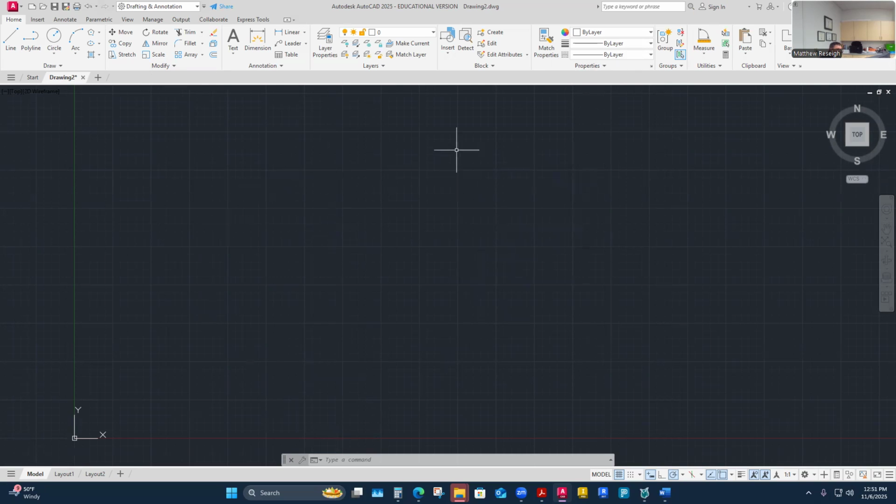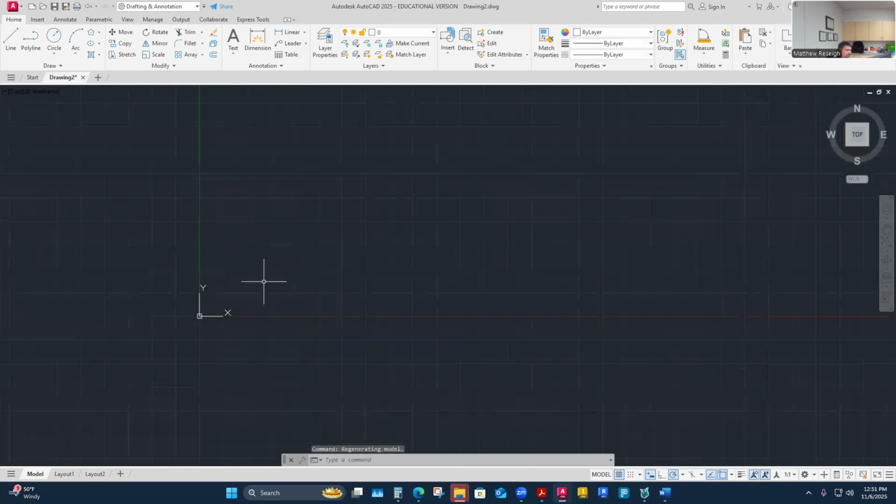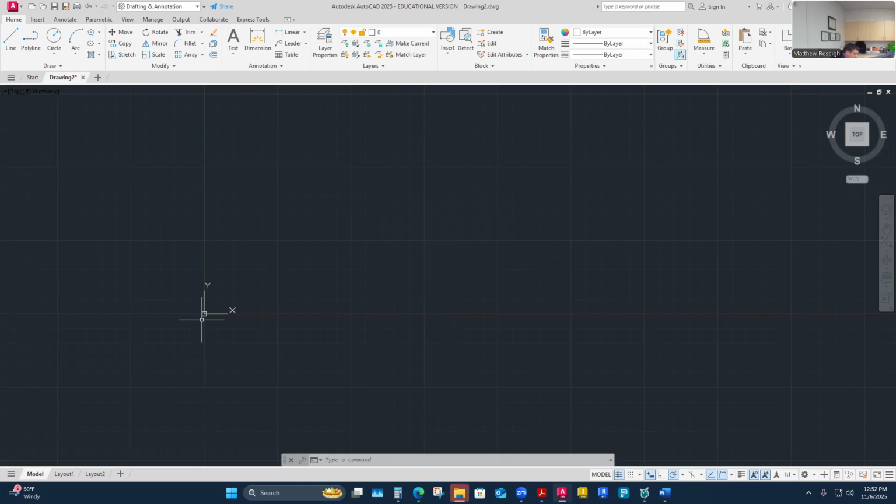Then I'm into my model space. So let's talk through this. What you're looking at is something that could be as big as the universe, the model space. So it has an XY. This is to help you keep your bearing a little bit. I never try to lose my orientation to XY. This is 0, 0. Your coordinate math is going to come back and haunt you here. Here's X and Y, and so it just has a 0, 0 point.